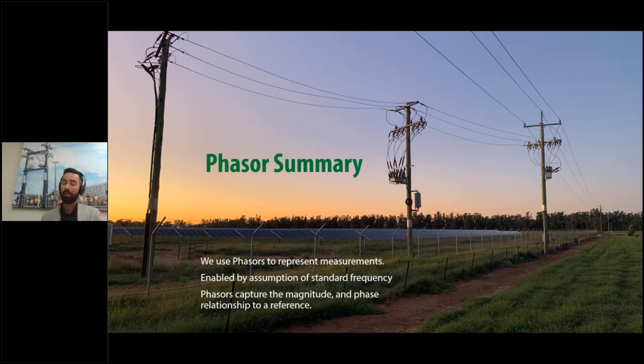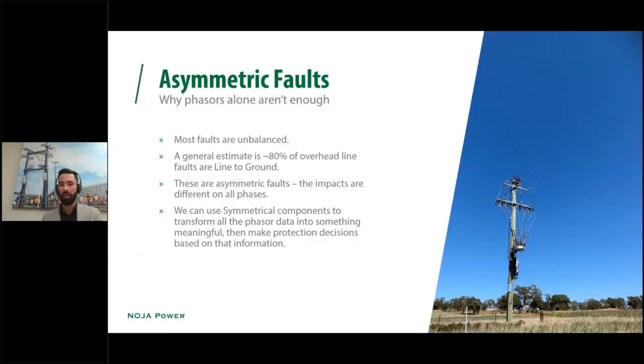And the main case is that things are not always so perfect. The problem is that phases alone are certainly not enough, because the majority of faults that we have in the network are asymmetric or unbalanced. So just because you know something about one side of the phase or one phase alone, you don't necessarily know what's going on the other sides, or in the voltages, or in the currents, or the relationship between those. Now, if 80% of the faults don't have that relationship,